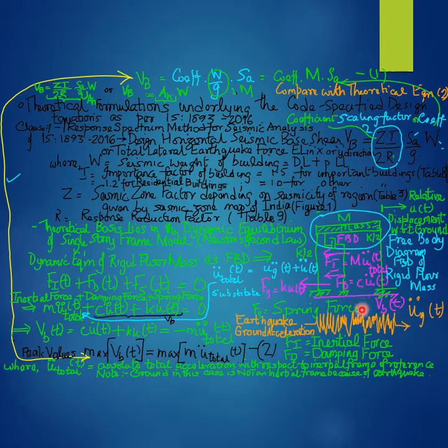When we consider the free body of the entire single story frame, one can verify that the theoretical dynamic base shear V subscript small b, a time variant function, is equal to the sum of the dynamic damping force F subscript D and the dynamic spring force F subscript S, both of which are also time variant.